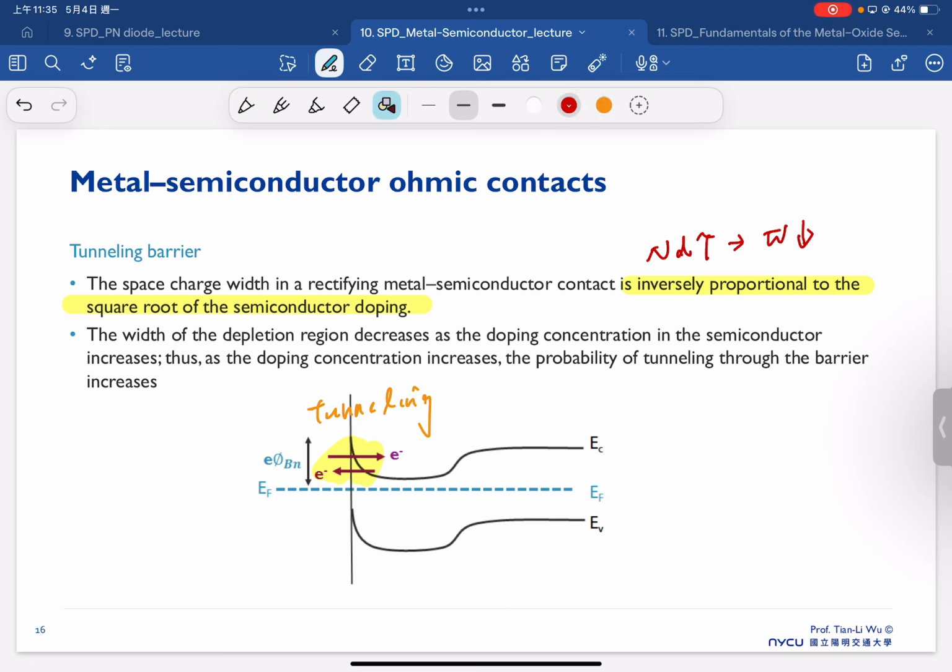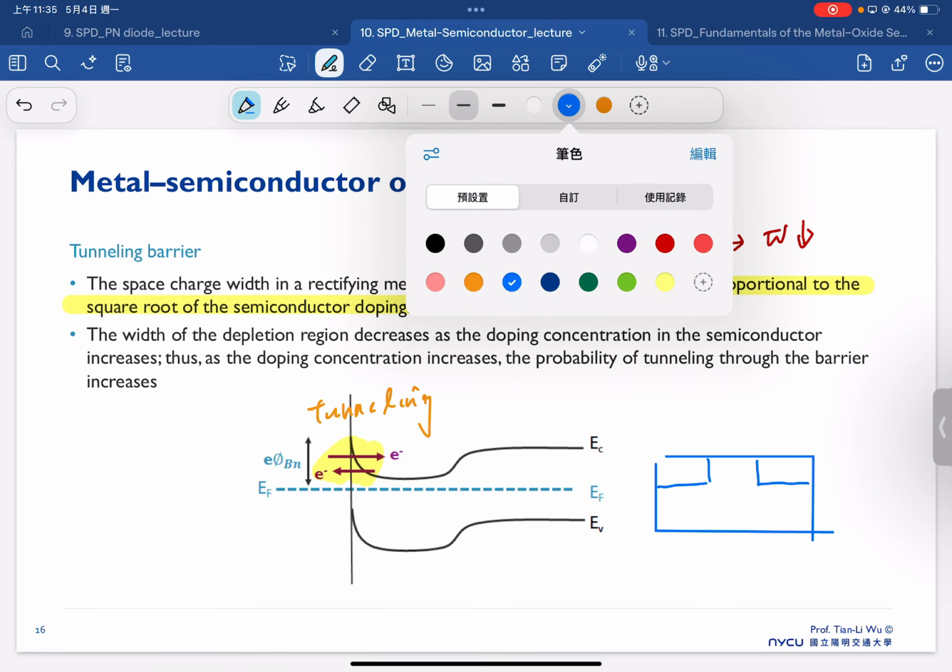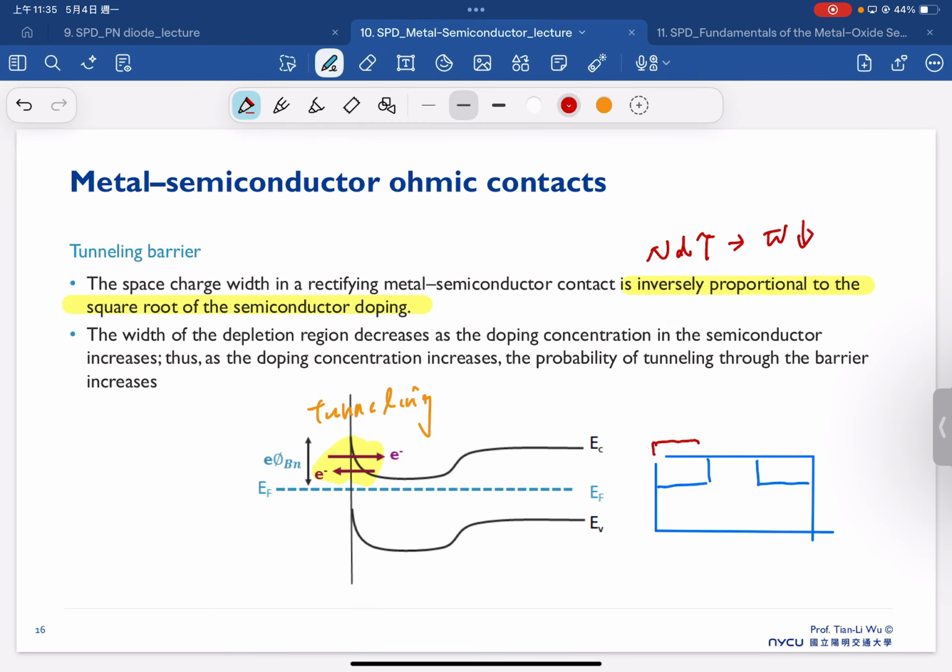In most of the semiconductor cases, we consider this as a metal. Actually, we always prefer to make this source junction highly doped, because normally this is a contact resistance between the metal and the junction.